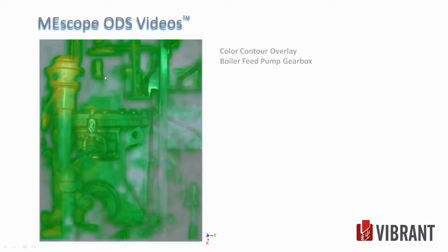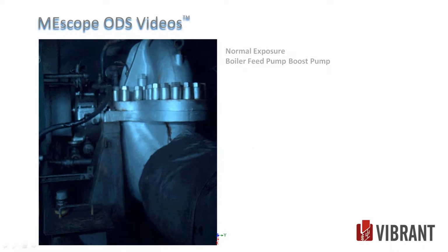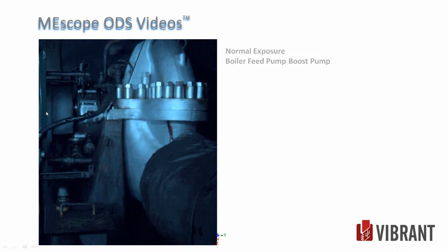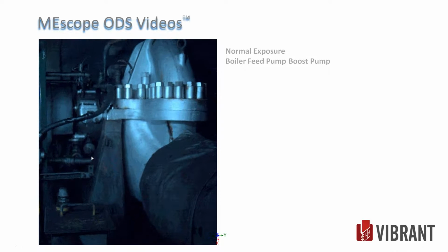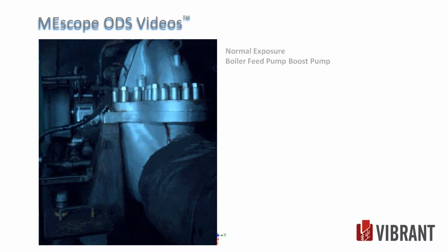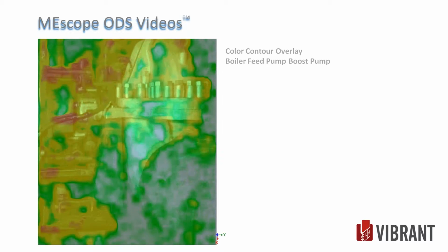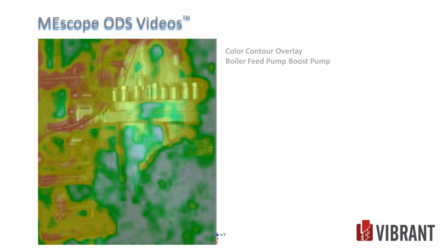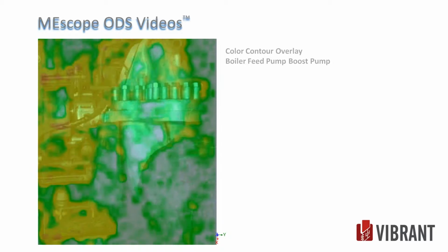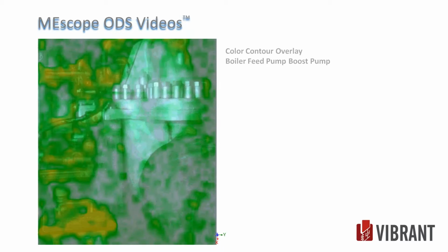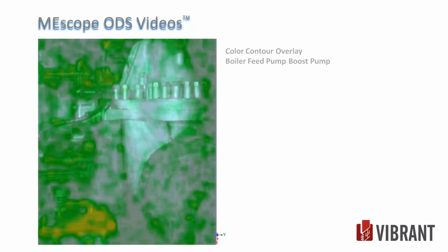Nothing real exciting in the gearbox to look at or problematic. This is the boost pump, here's the coupling, and the gearbox is on the other side, and it's bouncing around as well. Everything is in phase on this one for the most part. All the piping lines going to and from the units, and everything's moving together. So no misalignments, a lot of motion, no loose feet, anything like that. We couldn't find anything that would cause this except for the deck is moving.